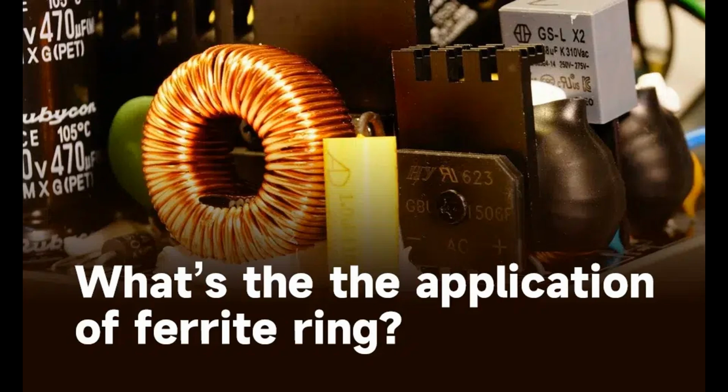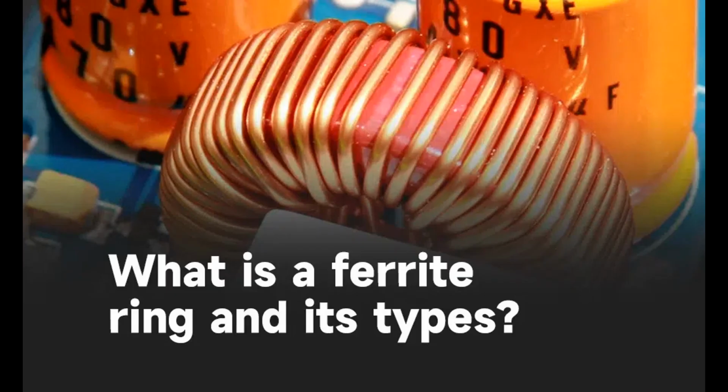B. DC-DC converters. Role. In DC-DC converters, ferrite core inductors are used to transfer energy between different voltage levels. They help in maintaining a stable output voltage by smoothing out the fluctuations in the input voltage. Benefit. They improve the efficiency of the conversion process by minimizing losses and handling high switching frequencies.